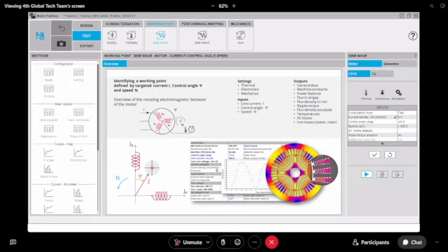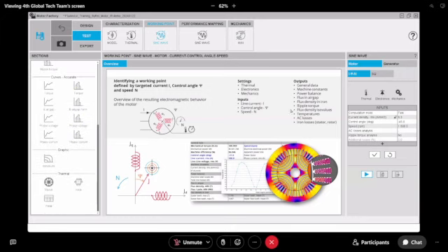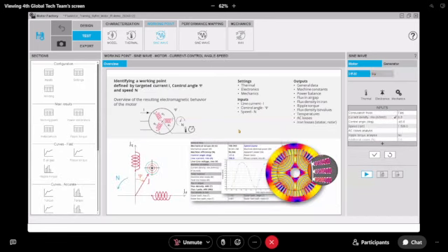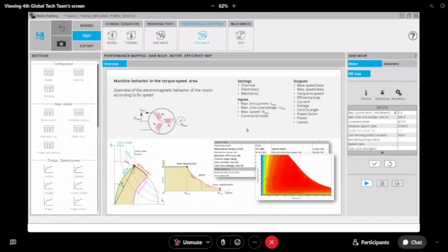So we'll try to manage the location, especially of the flux barriers, to reduce the saturation on them. And this is the only test where you have this iso-value, the ICN test. Okay. Then the efficiency map, at the end of the day, this is what you want to do.